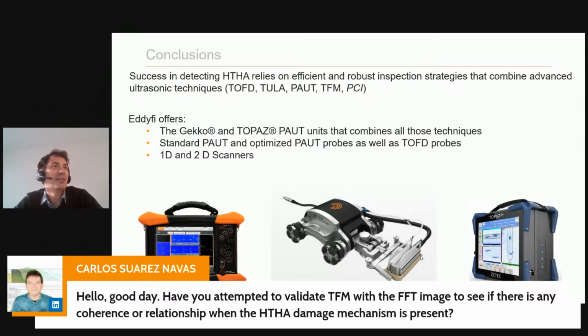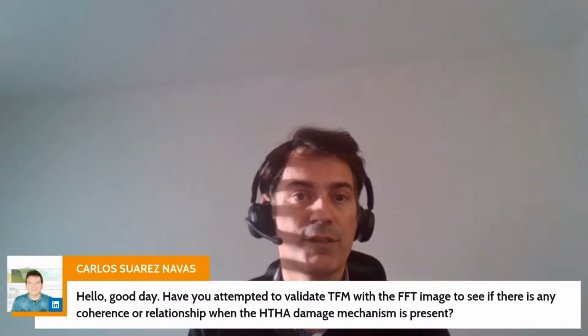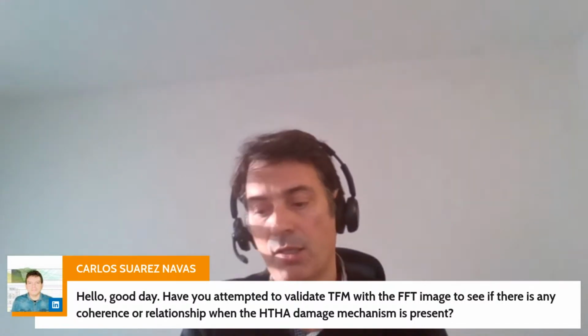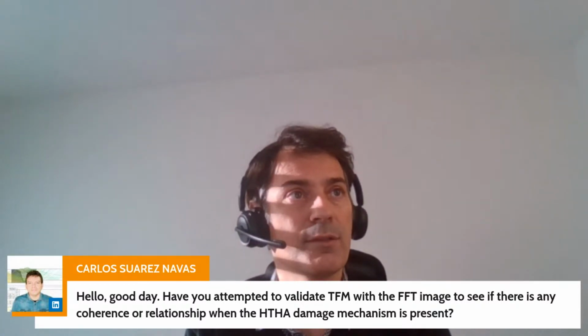All right. So, hi, Carlos. Have I attempted to validate TFM with FFT images? Not in depth. I tried to do it a little bit. I didn't see a lot of correlation between TFM and FFT, and I think the difficulty here is that when you do a Fourier transform, you need to make sure that you have a very nice surface condition and everything, and that's probably why some of the spectral analysis methods in the old API were not reliable. But I don't have a lot of experience with it, to be honest.